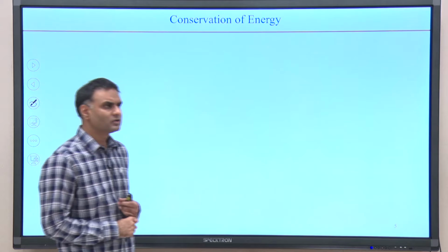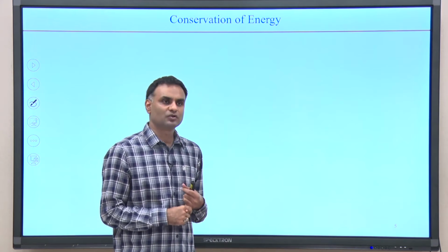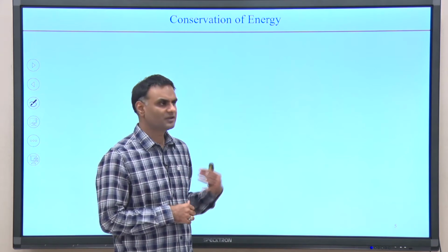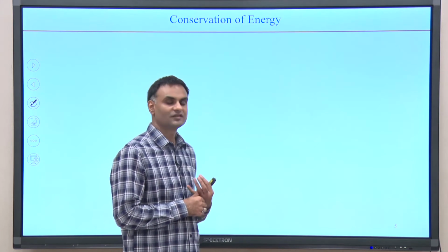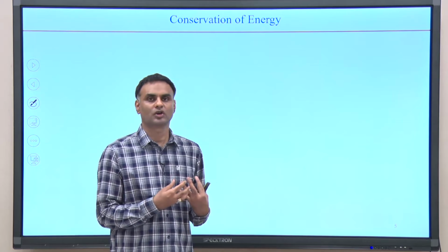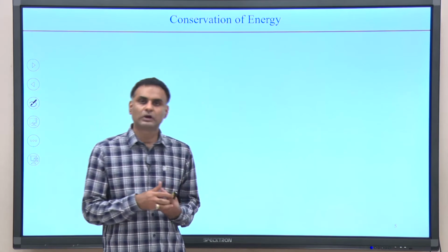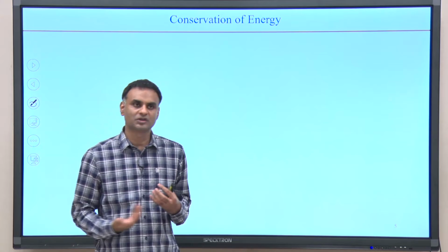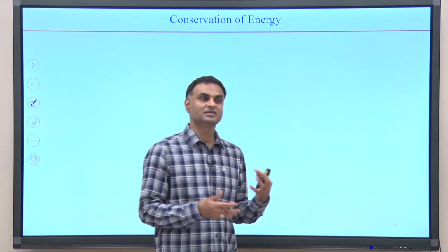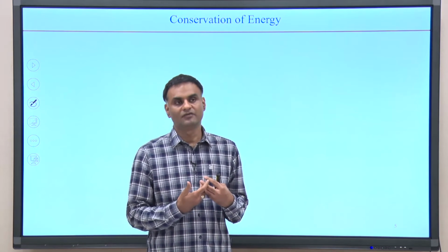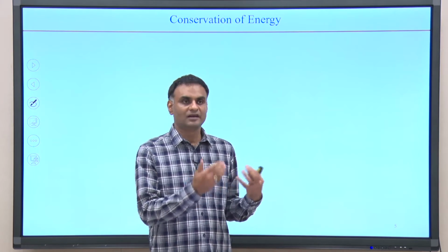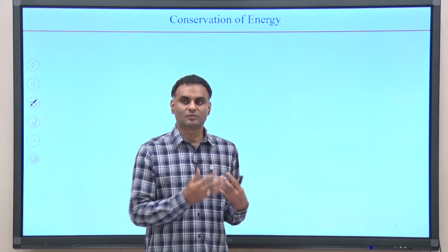And the third law is conservation of energy. When we talk about incompressible flows, and if the flow is isothermal, we do not need conservation of energy, until we are talking about problems related to heat transfer. But when we talk about compressible flows, the density is not a constant, and we need to relate density with the properties of the fluid.